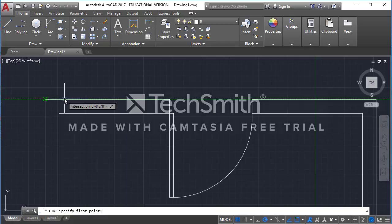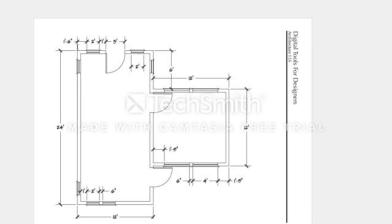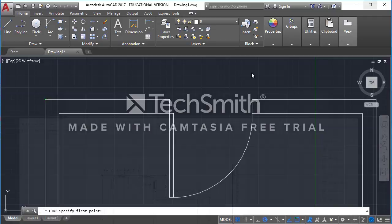But the nice thing about this is, if you notice right here, it's telling me that I'm 8 3/8 of an inch away from that corner. So as I move my mouse down, it's telling me how far away from that corner I am. I hover right above that corner, and as I move it in any one of these directions, looking for that green dashed line, it will tell me how far away from the corner I am. As soon as I get it, if I go over to my floor plan, I notice that my window starts at 1 foot 6 inches from that corner.